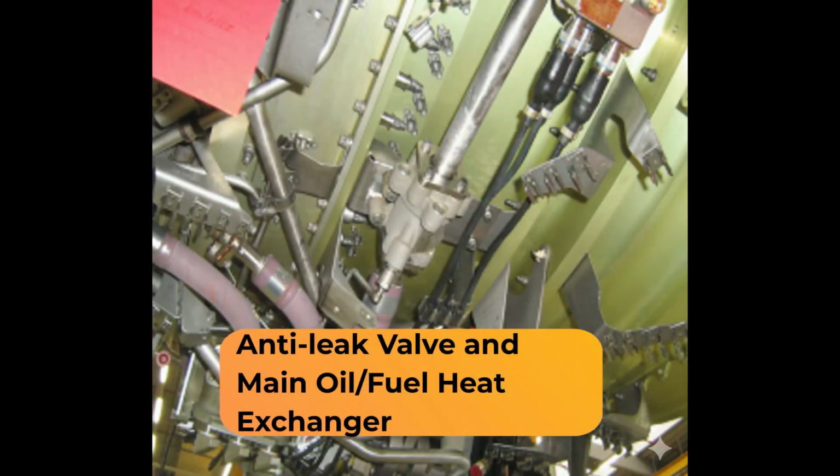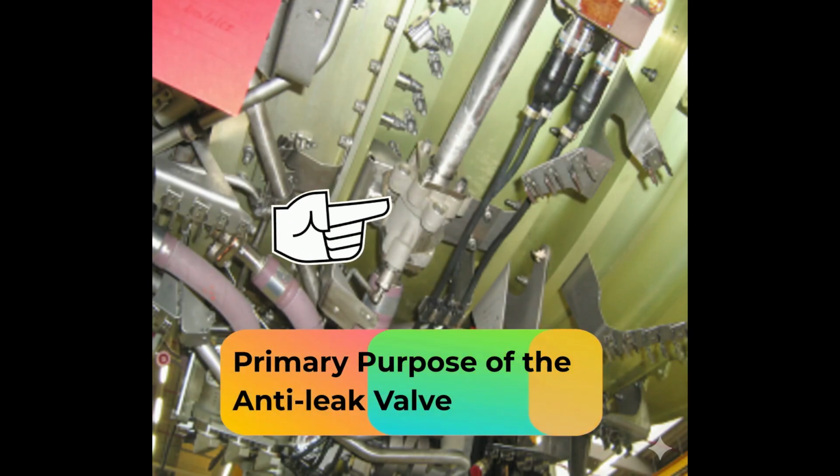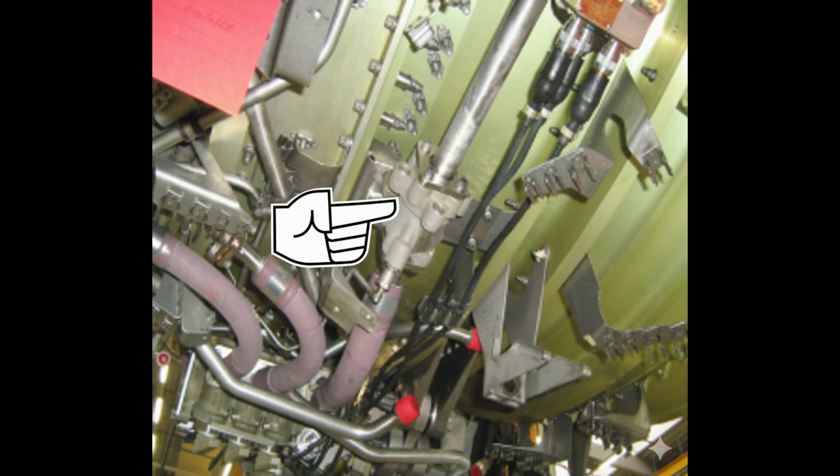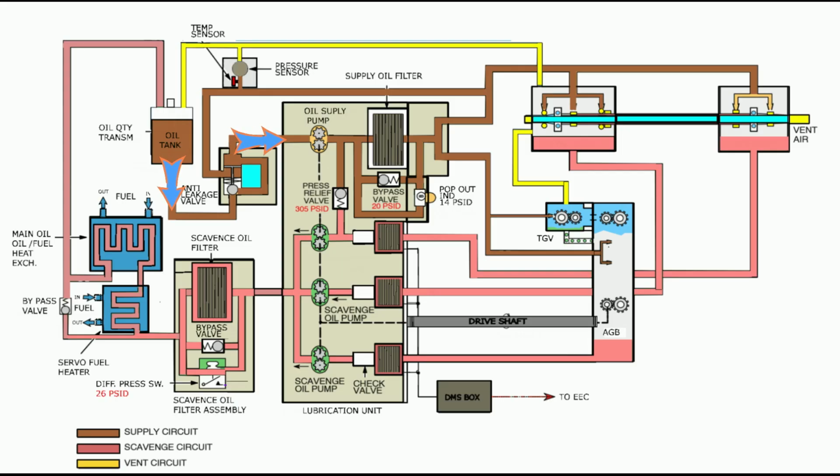Anti-leak valve and main oil fuel heat exchanger. Primary purpose of the anti-leak valve. The first objective of the anti-leak valve is to prevent oil leakage from the oil tank into the lubrication system when the engine is not operating. Since the oil tank is positioned higher than other components of the lubrication system on the engine, gravity could cause oil to flow into the system after engine shutdown, resulting in a decrease in the tank's oil level. Therefore, the anti-leak valve also functions as an anti-siphon valve.